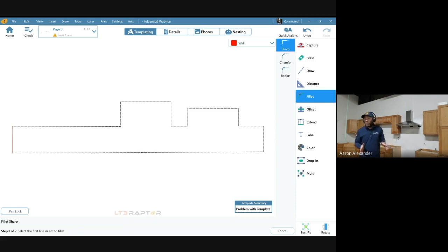Now, we all know that when it comes to drywall corners, right, we teach you guys in a horizontal situation to shoot 3 inches out, right in the corner, 3 inches out the other side. As you guys may have zoomed in and looked at that, that is always a whack angle in relation to the rest of the wall, because that guy typically floated 1/8 inch to 3/16 in on that corner of mud, right?